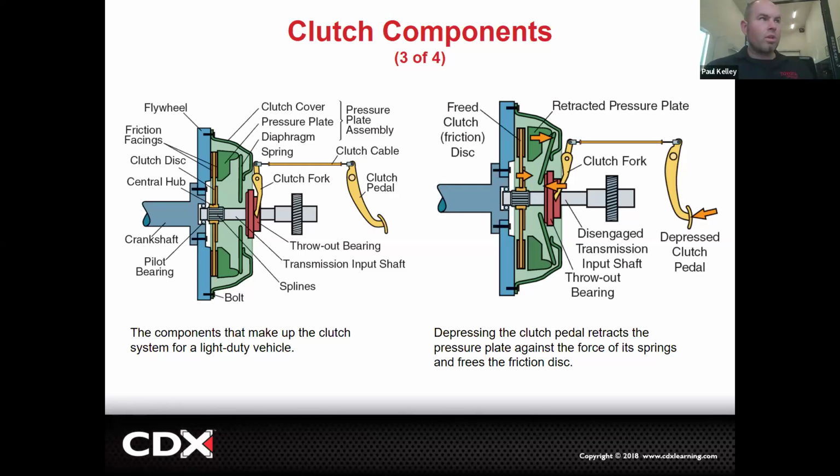Exact same thing with this pedal. When we're just slightly pushing the pedal, releasing the pedal, doing a little bit of this type of movement, if the pitch of that noise changes, we're talking about a release bearing, right? Just this little bit of movement right here will change the amount of force right here. That'd be like a release bearing. That's what I want you guys to remember, not whether it's up or down, because it's not really accurate.